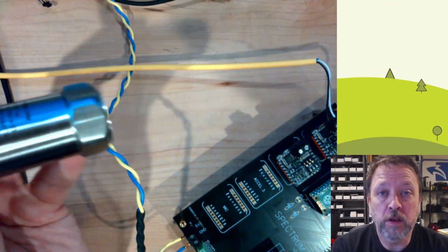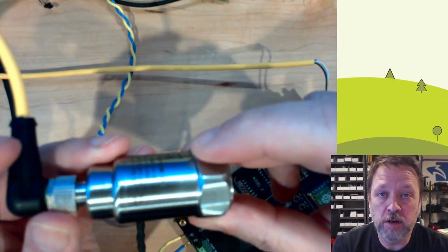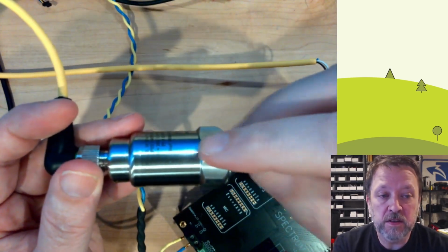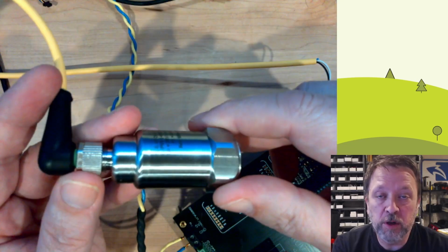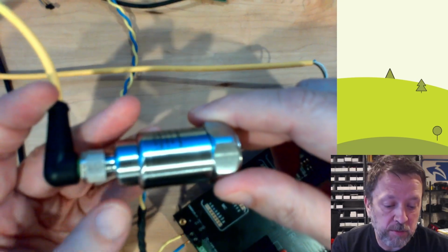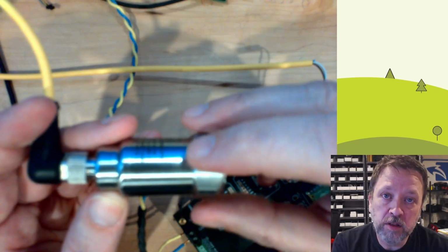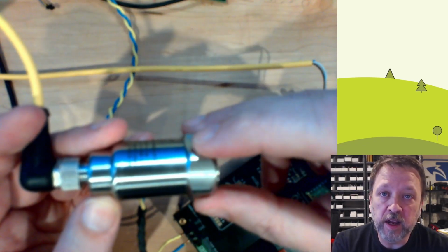Today, I want to talk just generally about how you go about building a custom solution or a custom device with .NET for an embedded type of project or an IoT project. For a project I'm working on, we want to measure vibration on machine tools. We want to do it in 3 axes, and so I've got these accelerometers. This accelerometer puts out 4 to 20 milliamps. So the question is, how can we do this 4 to 20 milliamp sensor at a vibration?